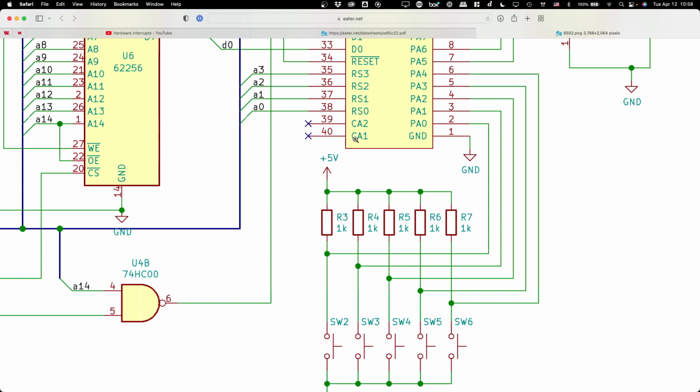So what this means is, I need to make a new version of this schematic. I'll see if he has the original of it that I can modify, okay? By adding this AND gate, and it's actually perfect that there's 4 of them, because how many are on each of these chips? 4, right? There's 5 buttons, but how many AND gates do we need? We only need 4 AND gates, okay? And that's perfect because how many AND gates are on one of the 7400 series chips? It's 4 dual input, single output.